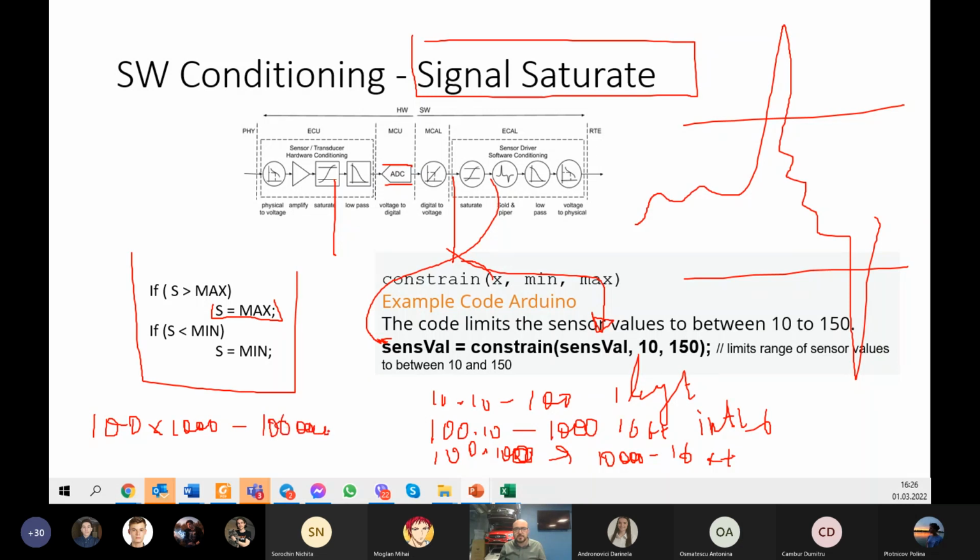So I'll have 100,000. That means the result will not fit anymore in the 16 bits. I will need bigger variables. Otherwise, in order to not use bigger variables and to use only the 16 bits, we can keep the calculus in the range of 16 bits.